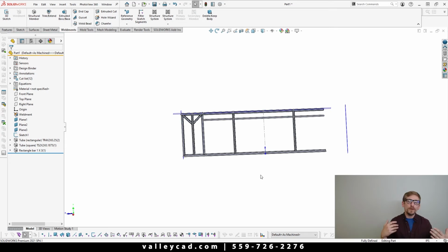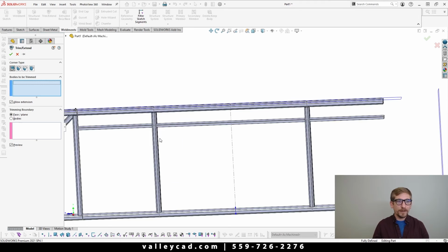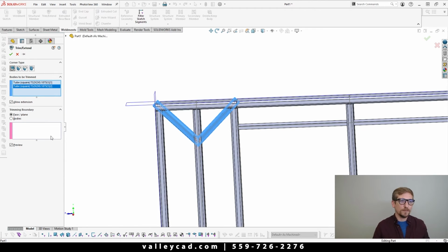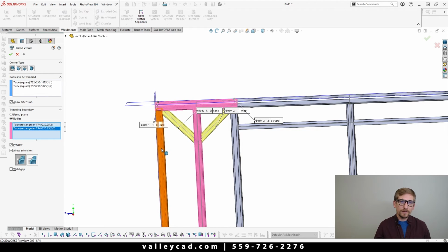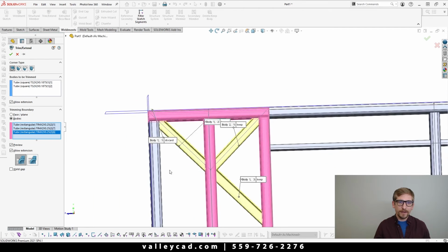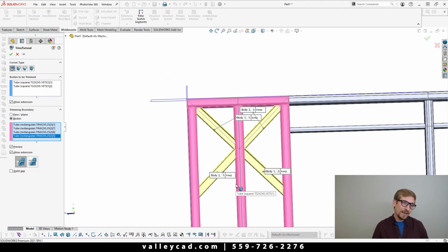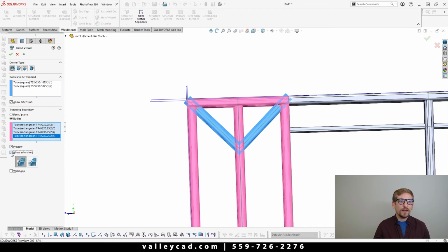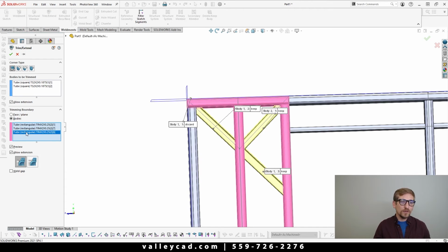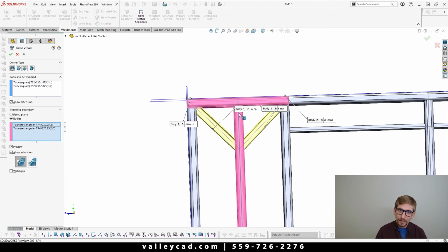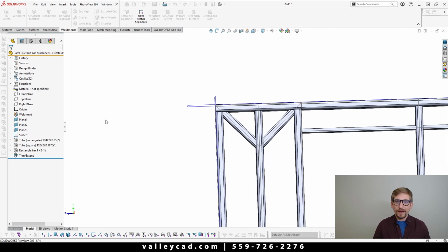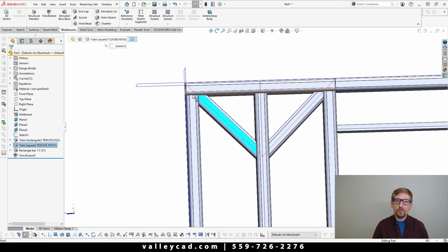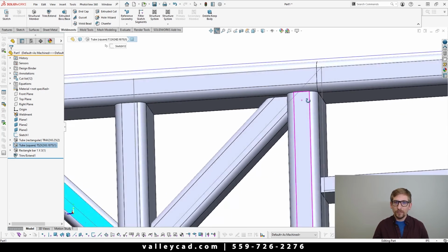So now what I wanna do is come in and create some trims on it. So trim and extend. So what we wanna say is bodies to trim. I want this one and this one to be trimmed. What I want to be trimming off of are other bodies. So if I click here, here, and also if I click here and here, you'll notice how SOLIDWORKS is extending it. I can make a really cool X shape, right? So if I uncheck, you'll notice that it's doing that because of these two vertical bodies. So if I delete those two, what SOLIDWORKS will do is actually make it so that it's cutting nicely on there. Now when I say okay to that, you'll see that SOLIDWORKS comes in and it makes one profile that matches up nicely all the way around this unit.